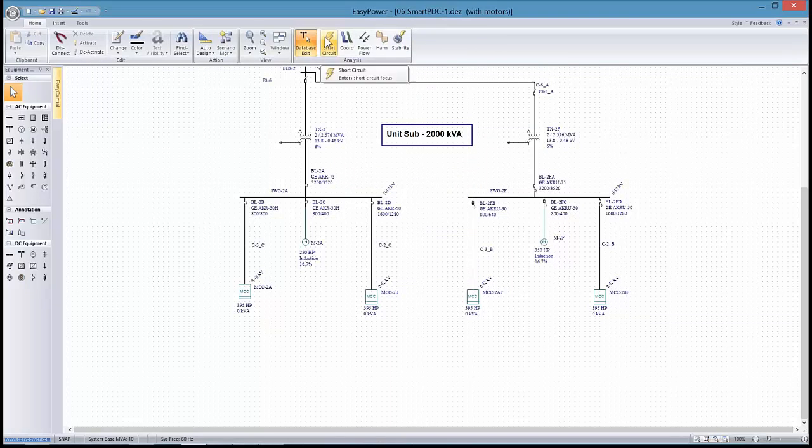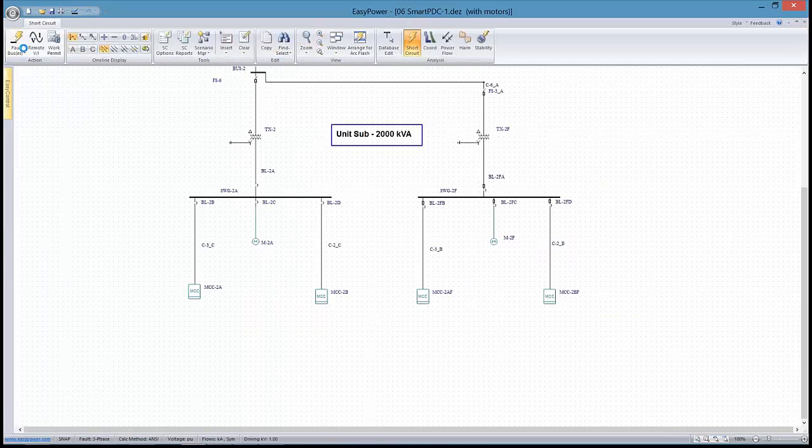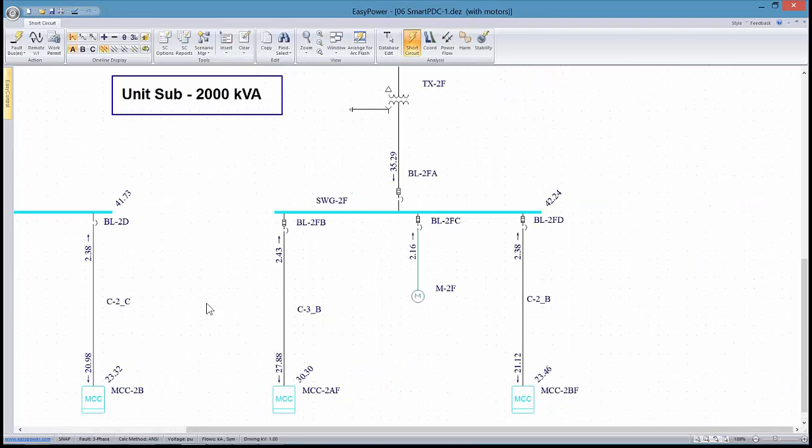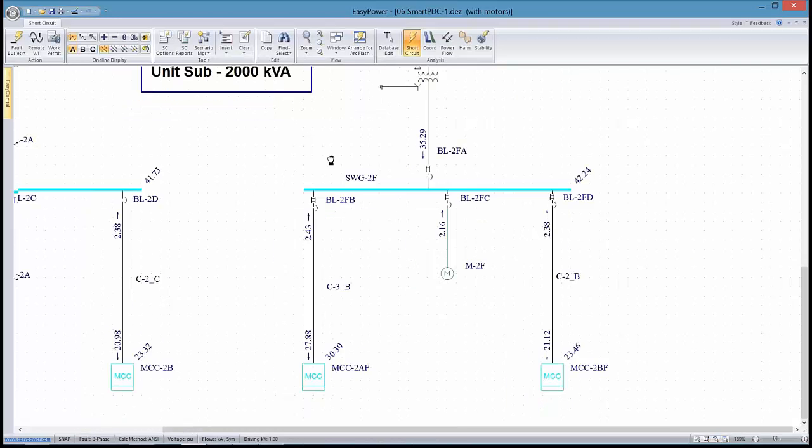And now as we calculate incident energy or look at the branch currents, you can see that we have motor contributions from each of these loads, and some are fairly substantial, maybe 5 to 8% of what the utility load is, or the bus load is on max current.